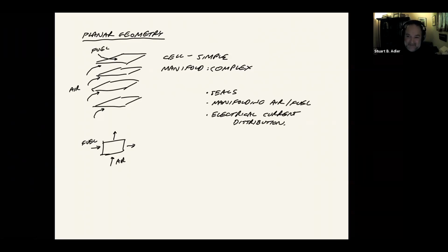So it's not good enough to just touch them in one spot and then expect them to be able to carry all this current in a uniform way. The problem is once current hits a cell, it's got to spread out. And the bigger the cell you make, the more that current has to spread out over the entire electrode. Unless that electrode becomes super thick so that you can easily conduct current laterally, it becomes harder and harder to ensure uniform current density.